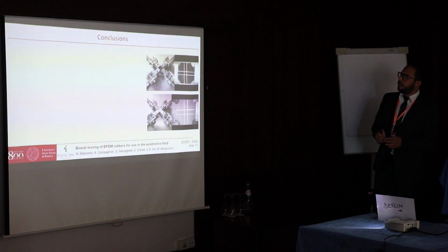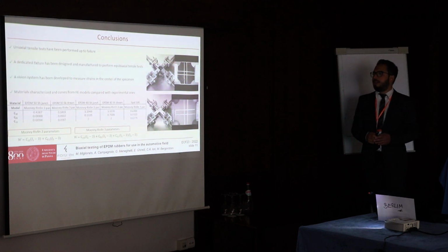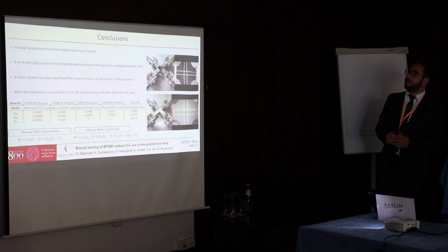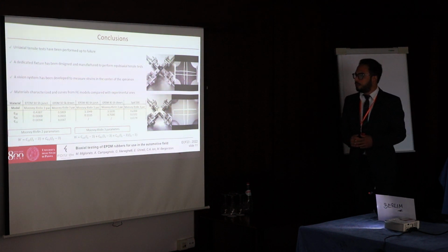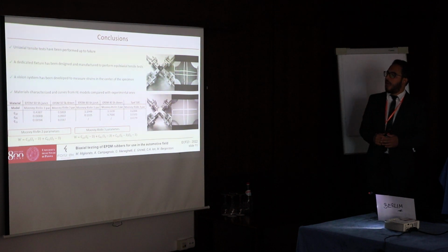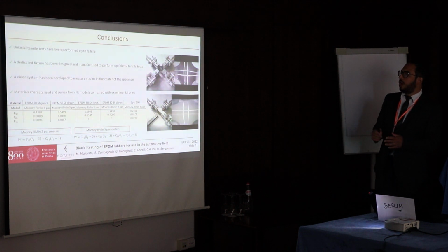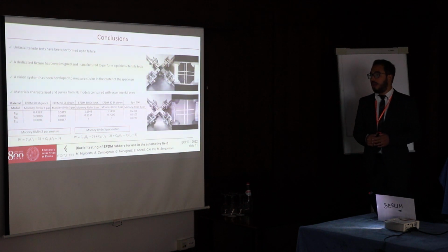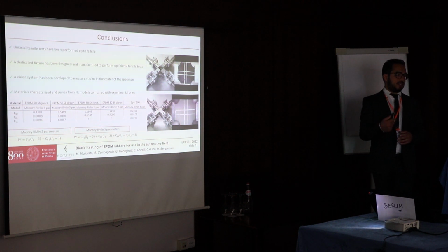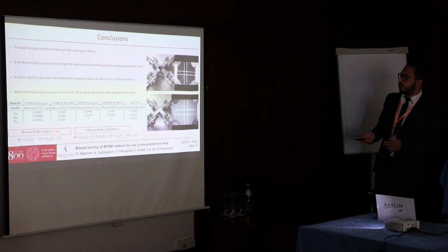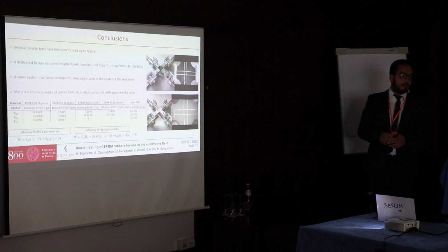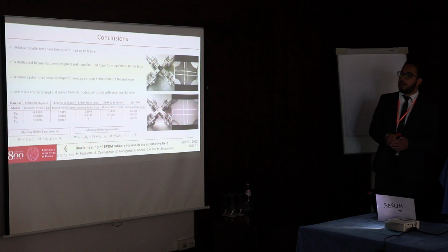So to conclude, uniaxial tensile tests have been performed up to failure of the cruciform specimens. A dedicated fixture has been designed and manufactured to perform equibiaxial tensile tests. A vision system has been developed to measure strains in the center of the specimen. Materials have been characterized in terms of strain energy density function, and the curves from finite element simulation have been satisfactorily compared with the experimental ones.